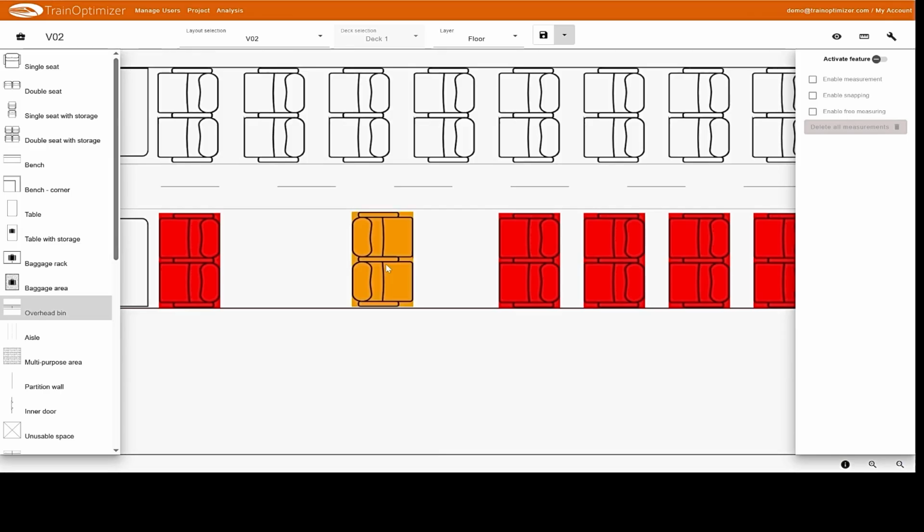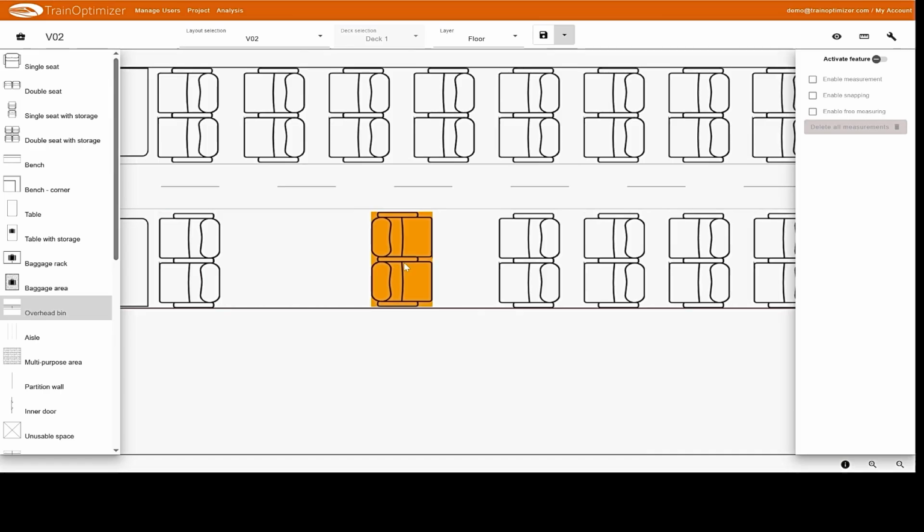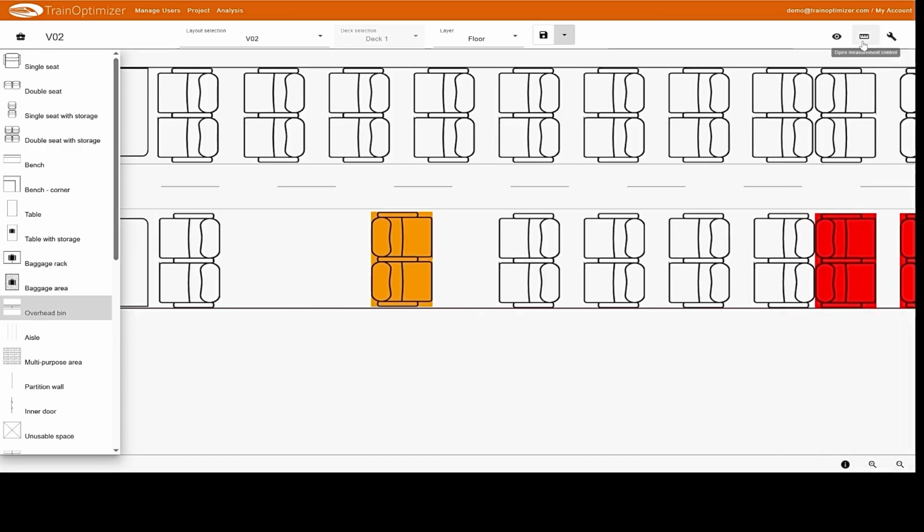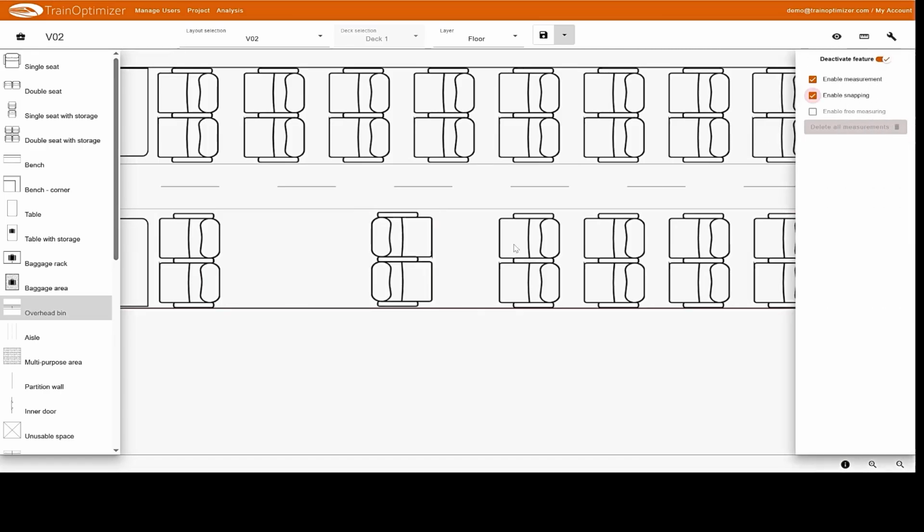Here you can also see the option of snapping to other elements, in this specific case, oriented to the upper seats or, as now planned, with a distance of 700 mm to the right. Now we have a reasonable size for a luggage rack and can take another measurement. The measured size is 1600 mm, so we can insert a luggage rack of, for example, 1.50 m.